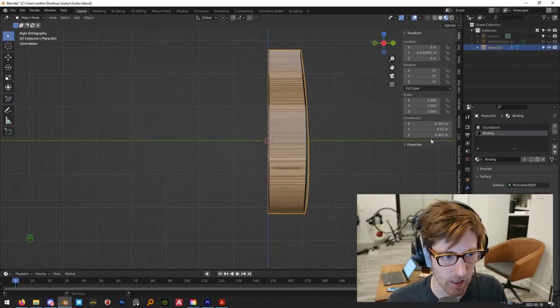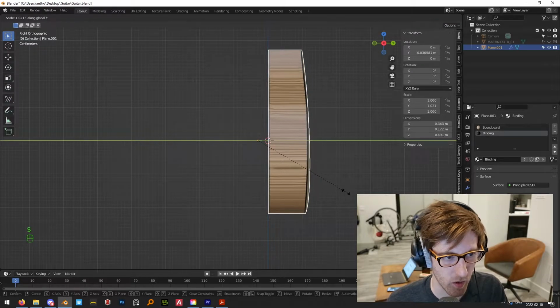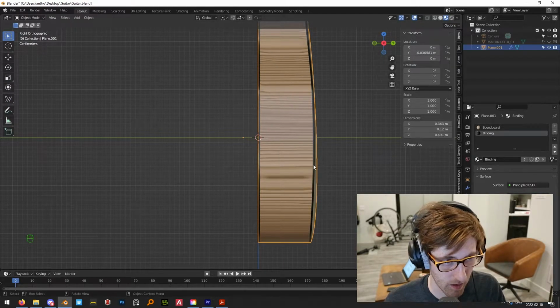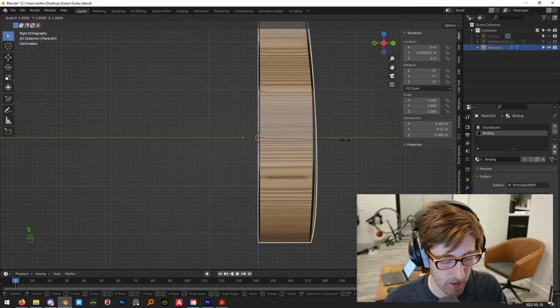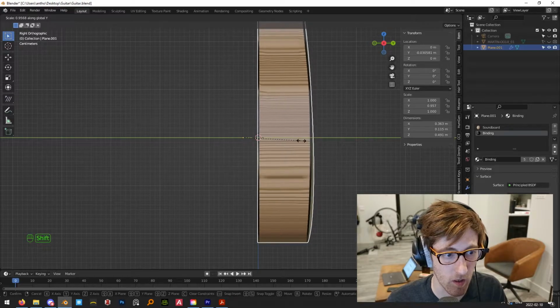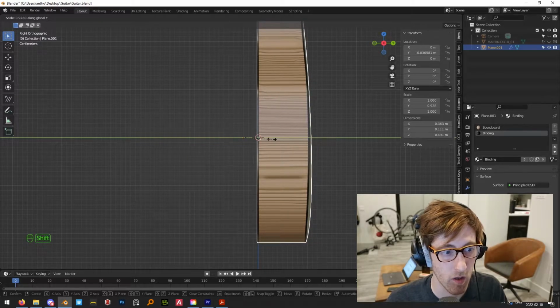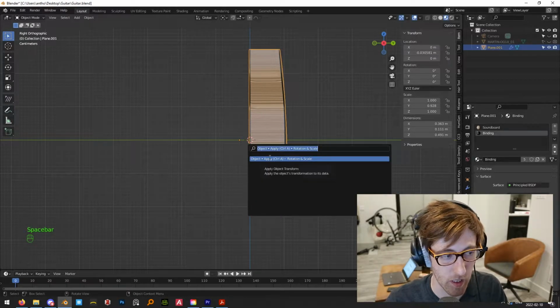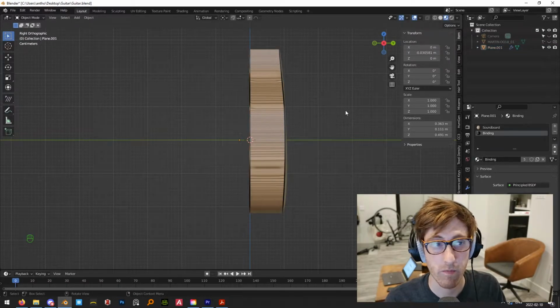We'll just click this, and actually I think it is pretty close already. It's 120 millimeters. So I'm just gonna select it in object mode, hit S and Y, and then I'm gonna hold Shift while scrolling until we get this thickness to 111 millimeters, and then Ctrl A, apply, rotation and scale.